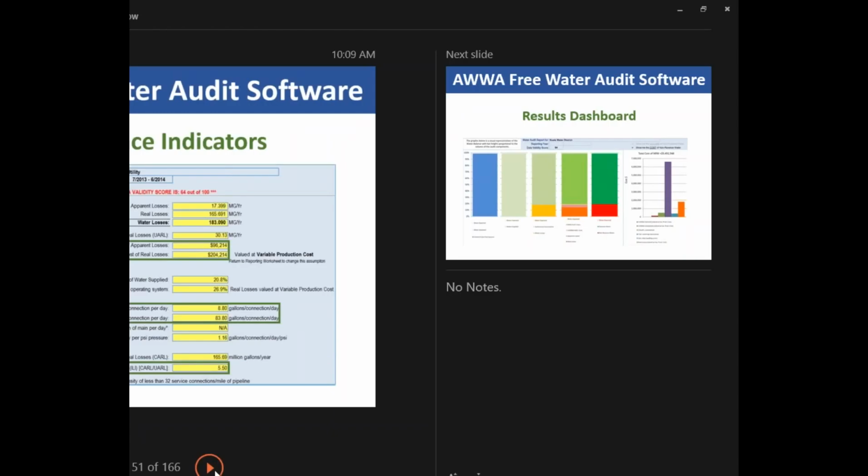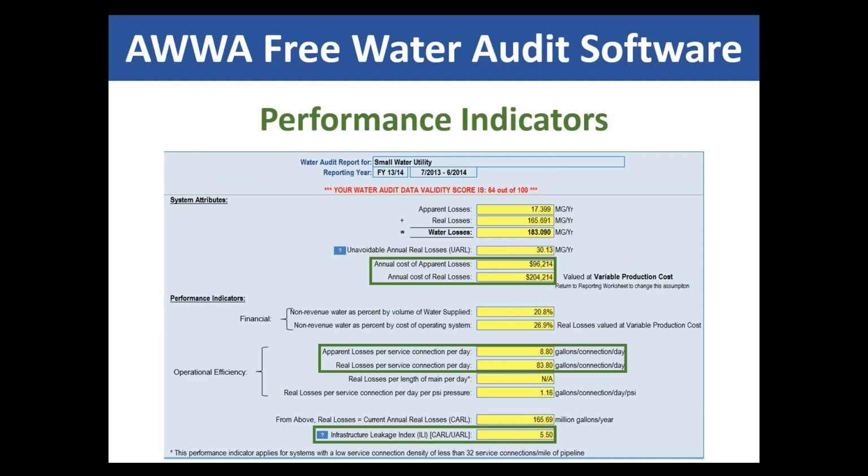This is a way for us to acknowledge in mathematical terms that all systems leak as one principle, and that there is a technical minimum volume of leakage that a system could achieve were it to employ all of the most aggressive leak monitoring and intervention and response strategies. The technical minimum is very rarely cost effective, so it's just a way for us to appreciate how we could perform if we needed to go that way. But generally between what is a technical minimum and where you are now is some sustainable threshold.